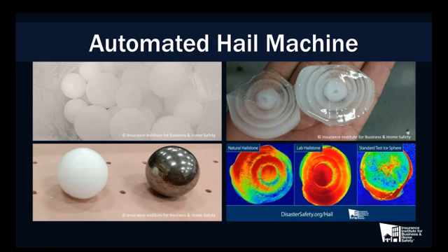We do have the capability now that we're collecting 3D models of hailstones to make molds to match those, to look at some of the shape effects, but I think we're a little ways away from tackling that. But the neatest image is that bottom right, showing a cross-section of natural hailstones. So the hot colors are the opaque ice that have a lot of bubbles. The cooler colors are where the background shines through, and it's a lot more clear ice with very little bubbles. And we see the example of a natural hailstone, one we produced in the lab, and then the FM 4473 clear ice. And you can almost get a feel for some of those microfractures that may happen in the middle of it, in that core of the cross-section.